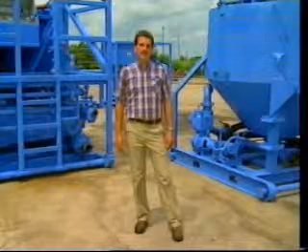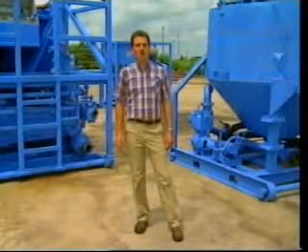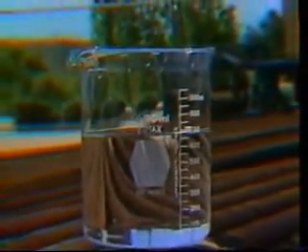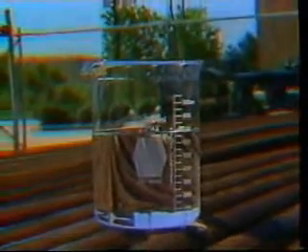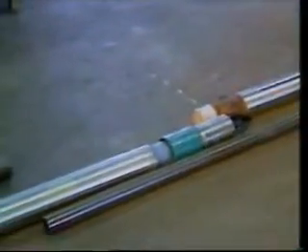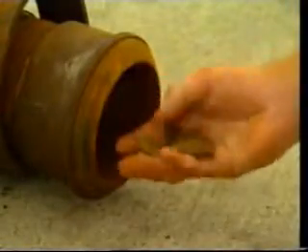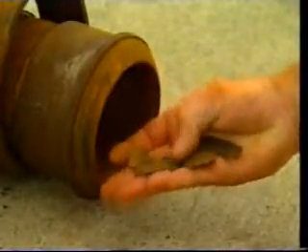In light of this, our discussion of downhole tools will deal only with the equipment and procedures associated with gravel packs. Again, it is emphasized that fluid cleanliness and quality is essential. Any tools that enter the wellbore, including casing and tubing, must be free of rust, scale, and other debris. The downhole tools must be inspected to ensure that they work efficiently in order to minimize the risk of tool failure and the number of trips in and out of the well.